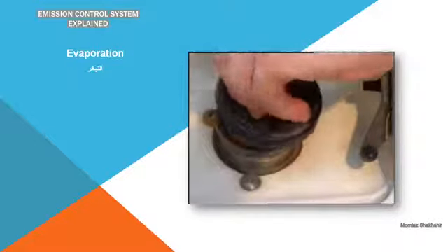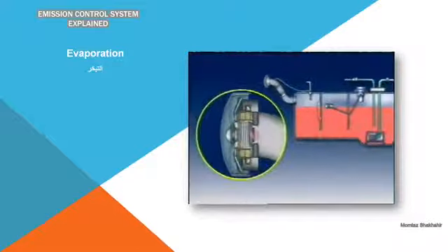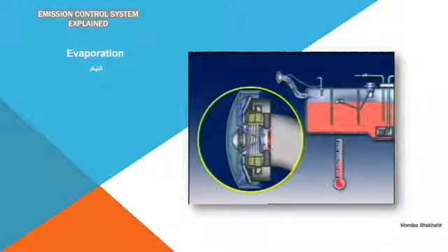Non-vented filler caps are designed to stop the exit of vapors. A vacuum relief valve can relieve low pressure in the tank when the temperature drops. This will also stop the tank from collapsing if its internal pressure falls below atmospheric pressure.